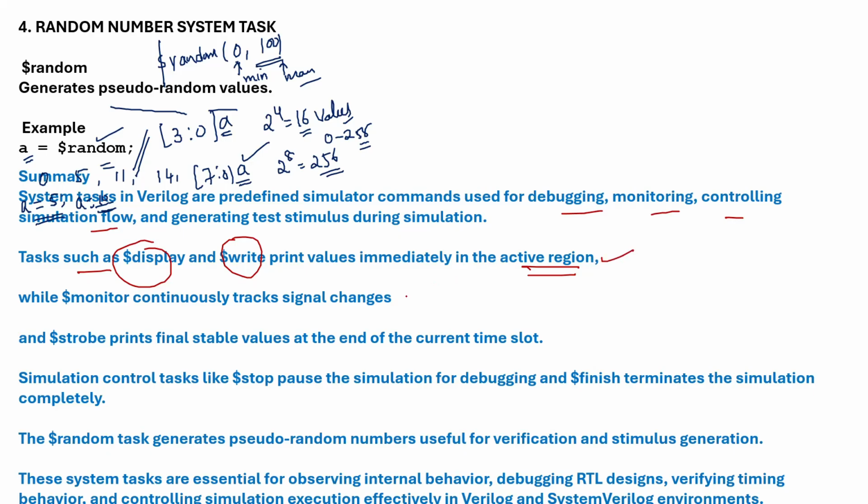And $monitor continuously monitors. $strobe and $monitor are executed in the postponed region, the monitor region.